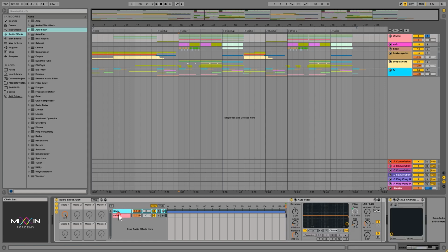So I'm sure that I'm not changing the sound, not changing any phase of anything using a really steep filter, because filters do mess with the phase of sounds, unless they are linear phase filters, like in linear phase EQs, which do introduce latency. So right now, I'm sure that once I turn all the way up, I'm not filtering anymore because all of the sound goes through the clean. So let's try that out.